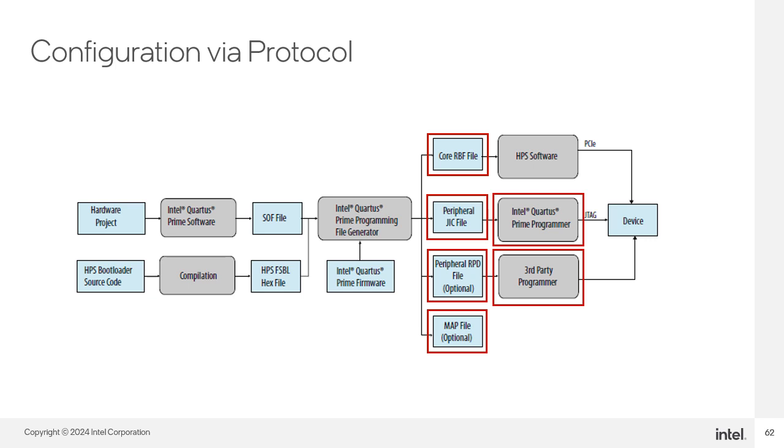The FPGA device is configured from the initial peripheral bit string from QSPI Flash, which brings up the PCIe interface on the FPGA. The PCIe host later configures the core fabric over PCIe. This includes downloading and running HPS FSBL. When using CDP, only the FPGA configuration first mode is supported.